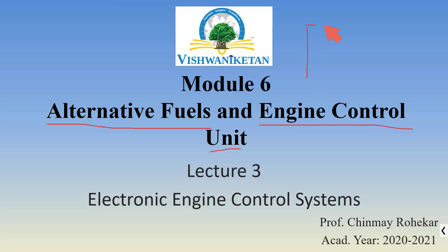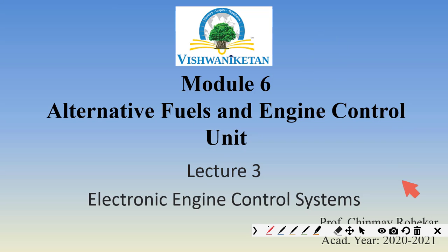But there are complete systems. As I told you, there can be several different control units inside one single vehicle, inside a single engine. Okay. So different engine control units are responsible for different functions. For example, one might be responsible for the throttle position. One might be responsible for the amount of fuel injected. One might be responsible for what is coming out of the exhaust gases. One might be responsible for the amount of exhaust gas recirculation. Thus, there are different engine control units and there are different functions. In this lecture, we will be seeing some of these functions which are included in your syllabus.